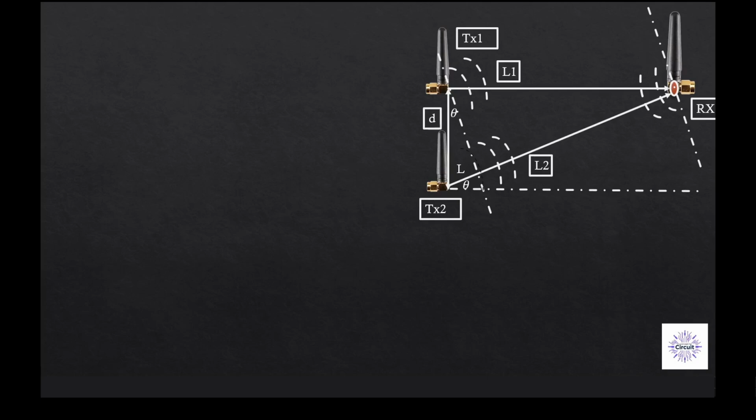This is advantageous because we can steer the direction of transmitting without physically moving the antennas. We can just change the phase relationship between the channels of the transmitter, or at the receiver, if we have several phased array antennas. By just changing the phase relationship between the channels, we can steer the beam without physically changing it.